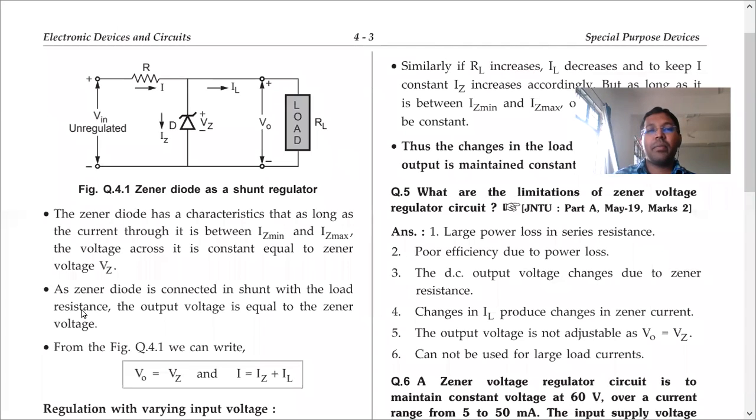Suppose what do you get in the plug point? 230 volts, right? Although you are connecting a fan, TV, fridge, tube light, it is still 230 volts, because there is a constant supply coming out of the plug point. Of course, that is AC. The same logic is valid for DC. The Zener diode maintains a constant voltage across it in the breakdown condition. Now, whatever you connect, still the voltage is constant.